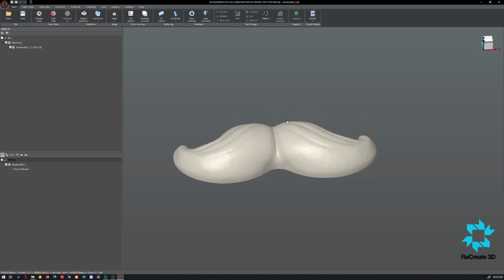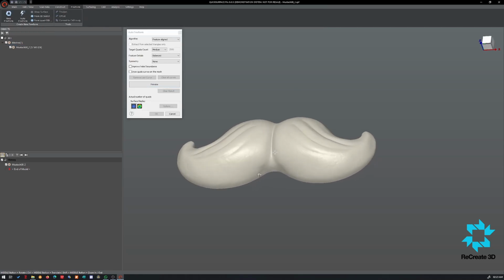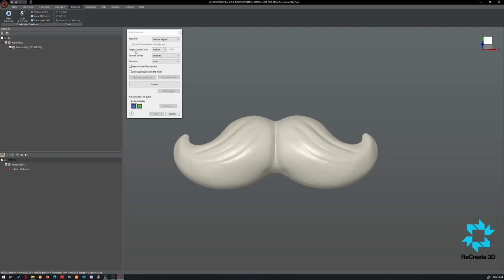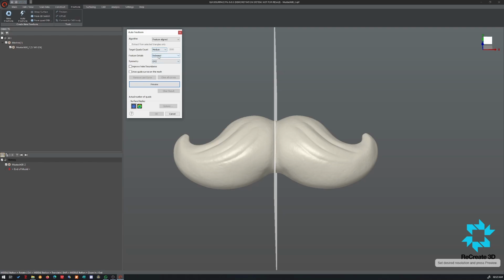So what I'm gonna do now, we're gonna go to Freeform AutoSurface, and we're gonna select here symmetry by ZY plane, and we're gonna select a quadrant. Let's keep a little bit higher feature detail, and let's start at medium, the sub balanced, and then we see. So we're gonna create now the freeform,